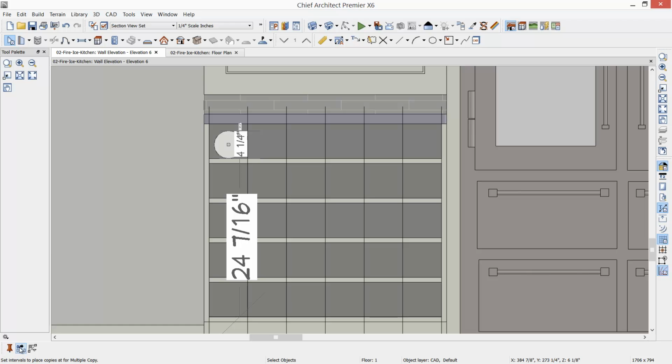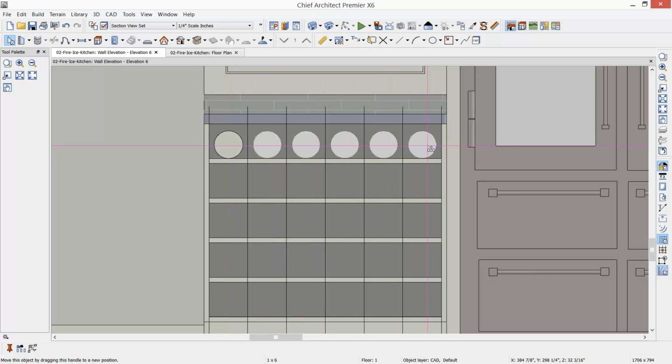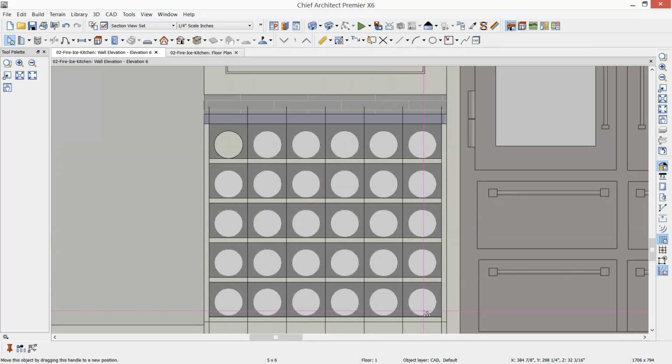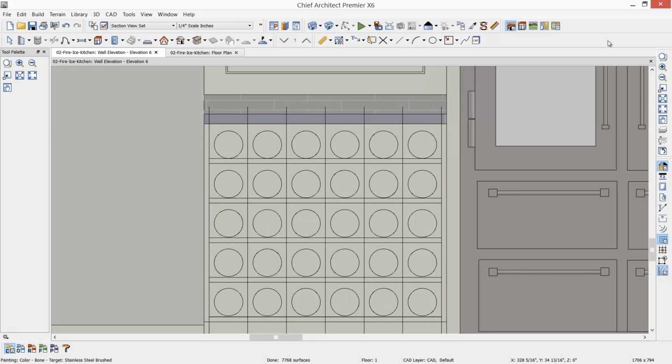So to make that happen, we'll select that tool, and I'm first going to hold down the Alt key. Let me turn off my temporary dimensions here. And let's go ahead and hold down the right click and then the left click. And that's generated the holes in the object. And if I use my material eyedropper, let's pick up the color off of this partition, apply it onto the solid, and now we can take our 3D view.